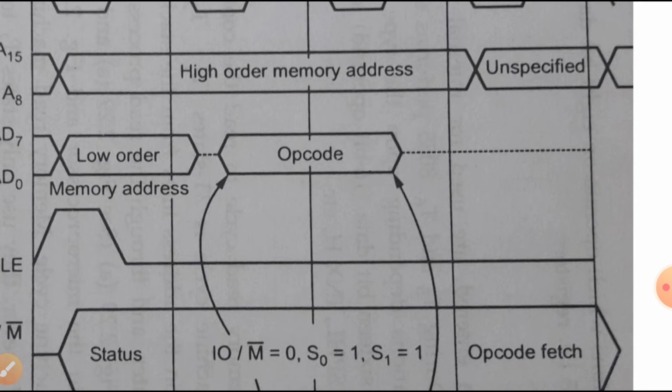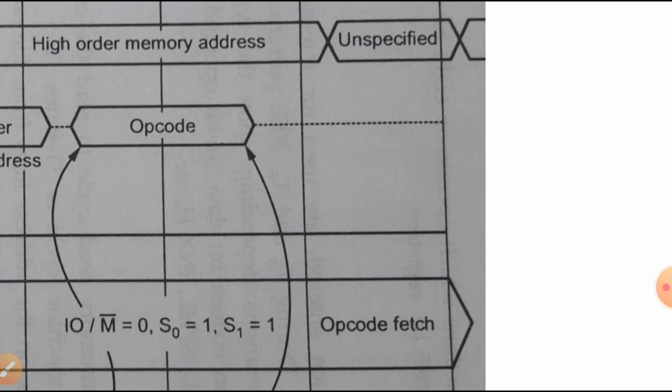And what happens in state T4? In state T4, the microprocessor decodes the opcode on the basis of the instruction received, and then decides whether to go forward to the T5 state or to enter the T1 state of the next machine cycle. One-byte instructions that operate on 8-bit data are executed in T4.